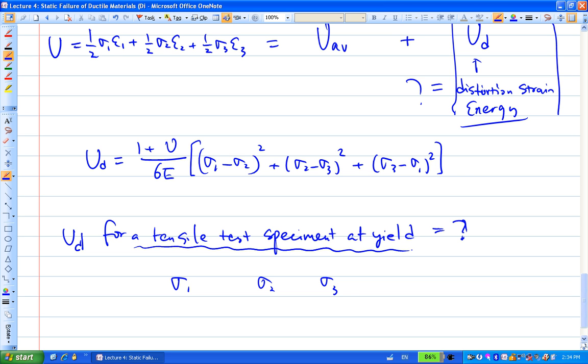You need to draw a Mohr circle first and then look at the Mohr circle. This is a tensile test, and the stress element has nothing else but sigma. At the yield, the sigma will equal SYT.